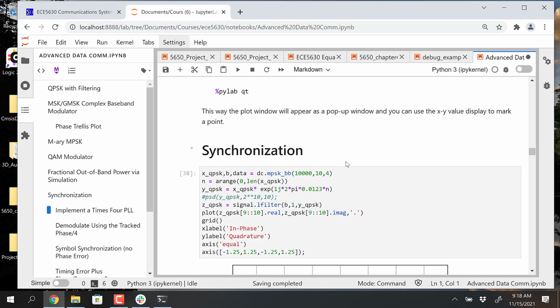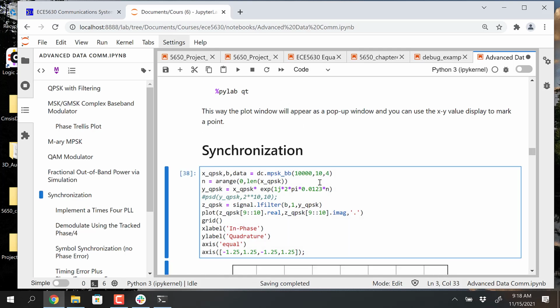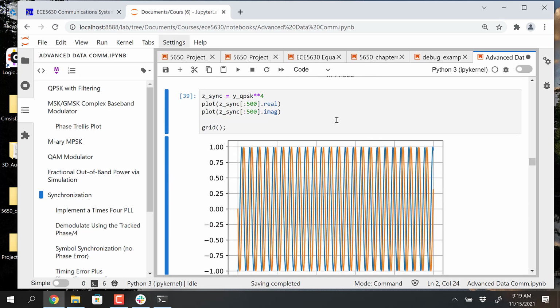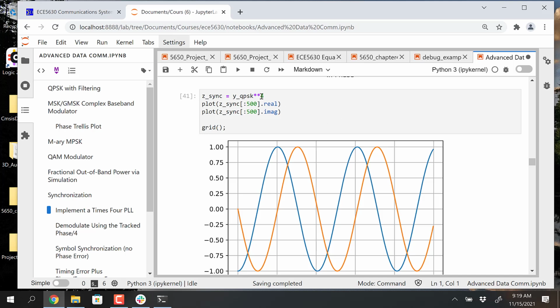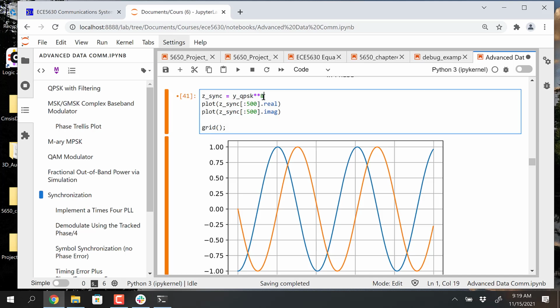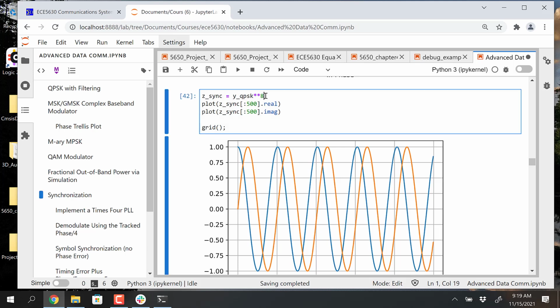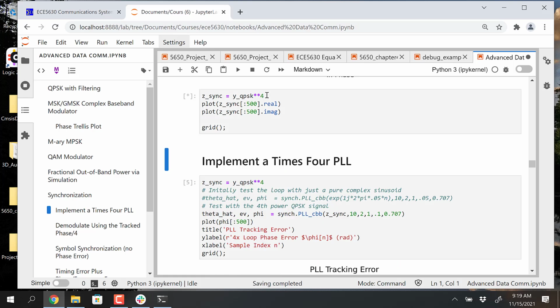Well, what did I do wrong? Oh, I took out a 0, that's what I did. And I guess if I put in 8, it's also going to work because I'm just raising it to a higher power, so it's going to create a higher frequency for the phase difference. So this is 8 times the true frequency error, whereas 4 is 4 times it. But this is going to produce more noise, so it's not going to be a very good thing.